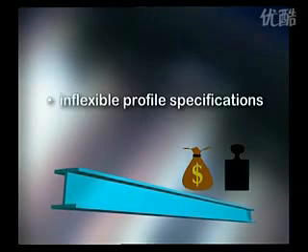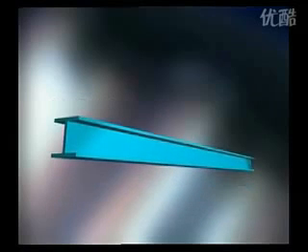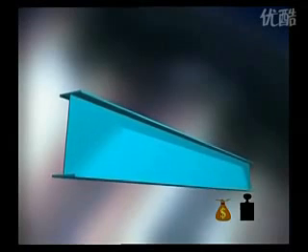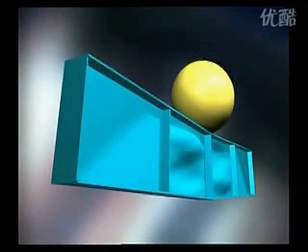They are standard solutions for details. However, the other side of the coin is that they have considerable disadvantages. Big differences in weight between the various dimensions result in uneconomic design weight. Individual sections may be used to achieve a reduction of weight. These can be wider and thus lighter. Despite the costly placing of stiffeners, they still tend to buckle if their depth is increased. This is the characteristic problem of plain webs. Web plates containing only a few plain sections or none at all would be ideal.